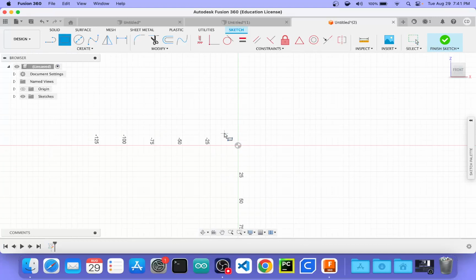So let's say I know I want to make a hollow container. This could be something like a big tray, it could be something like a case, it could be something like a tall, narrow box. One of the things all these containers have in common is that the sketch you're going to need to draw to make them is basically two rectangles. And so let's say I know that the inside dimensions of my container are going to be 30 by 30 millimeters, which is pretty small.